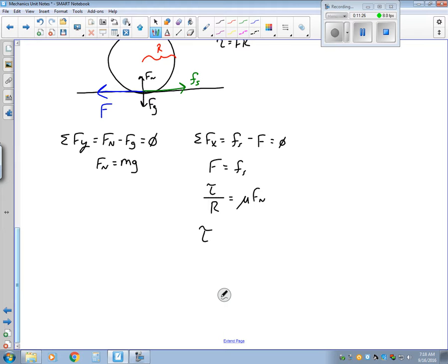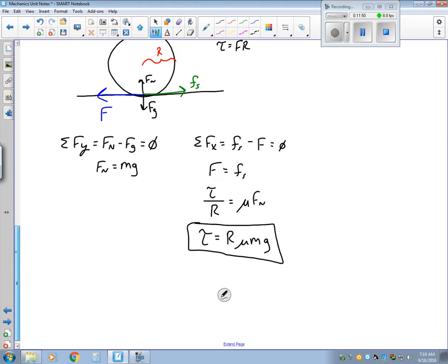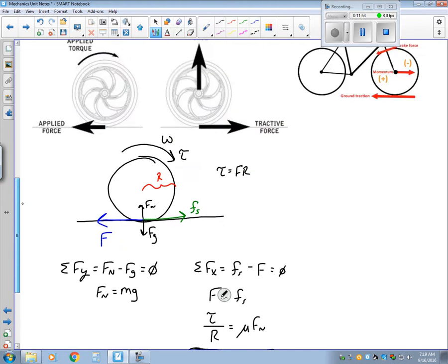So there we have an equation for a wheel. So we know that the torque, we can get that from the mechanical advantage and everything. We know what the radius of the wheel is. We should know how much weight is on it. And the trick comes to finding the coefficient. So that's a powered wheel.